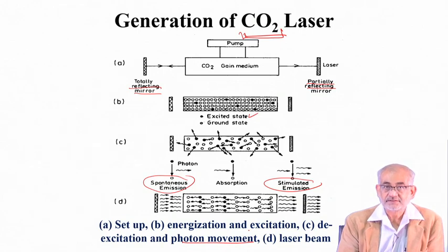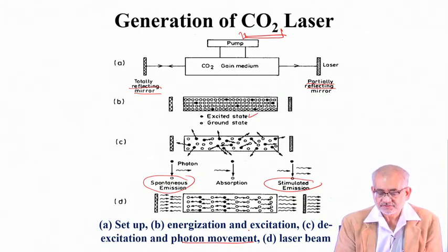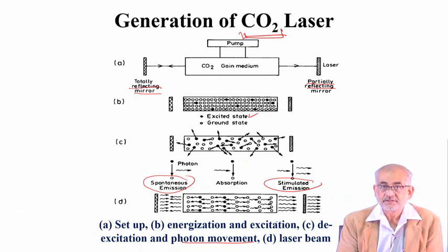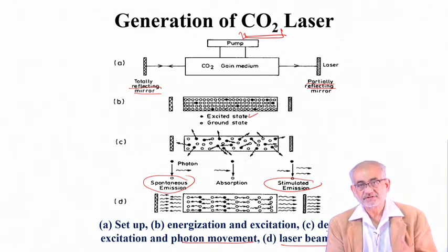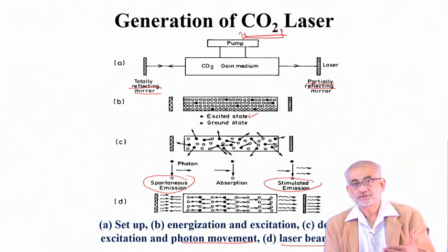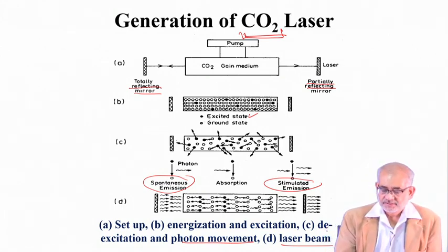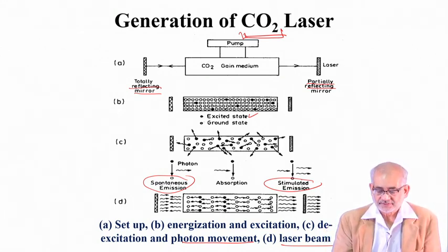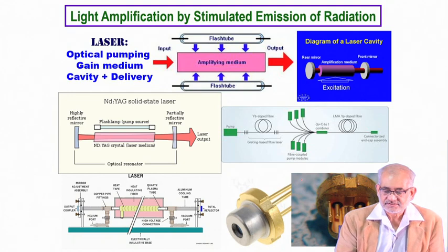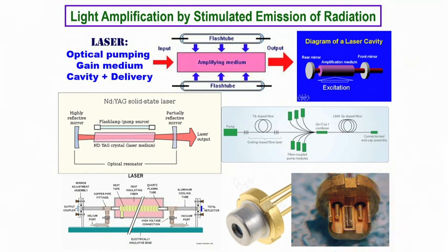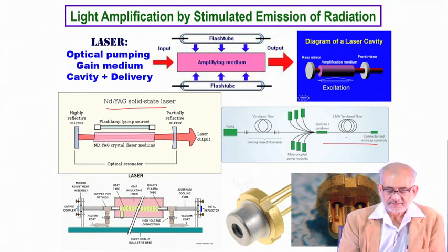And once they can make constructive interference or they are coherent with each other, then there'll be emission of laser initially, and the total intensity of the laser will depend upon the population that will undergo excitation, subsequently inversion, and also which will be able to maintain the coherence. So this is the process which is by and large true for all kinds of laser. I mean, be it CO2 laser or solid state Nd-YAG laser or diode laser or say fiber laser. This is one of the most common and the most widely used high power laser variety.